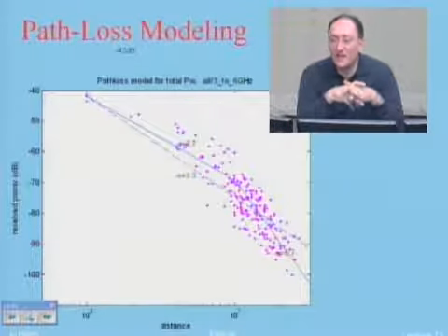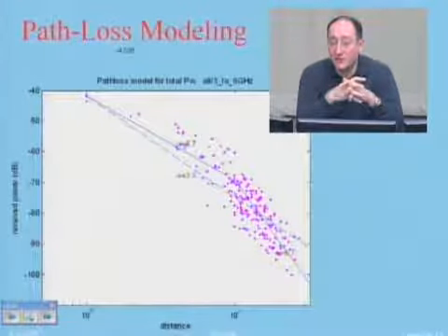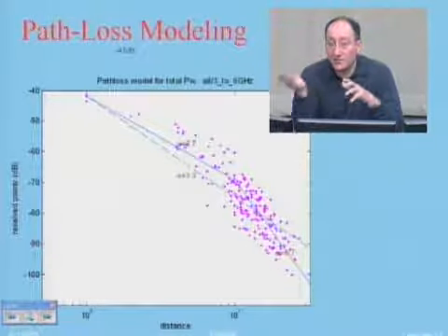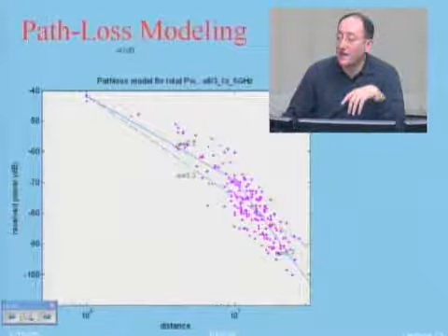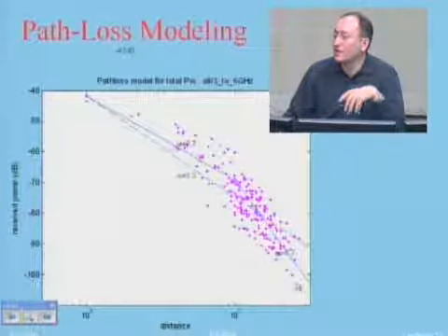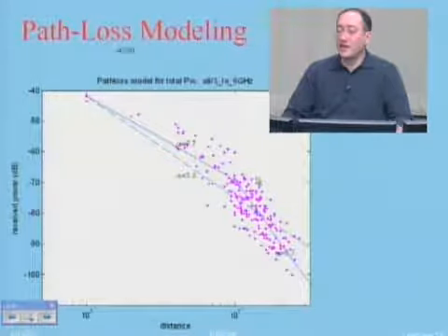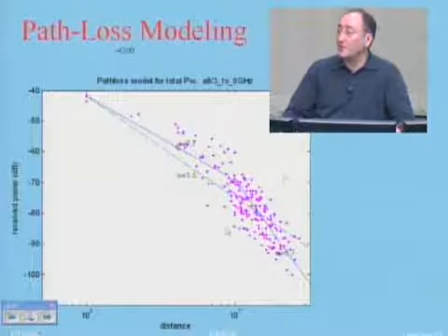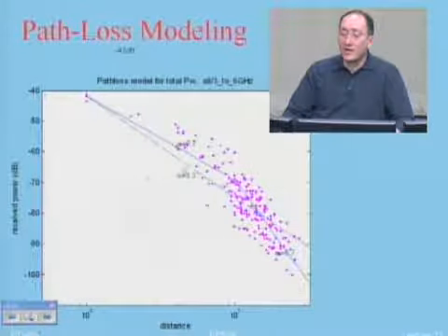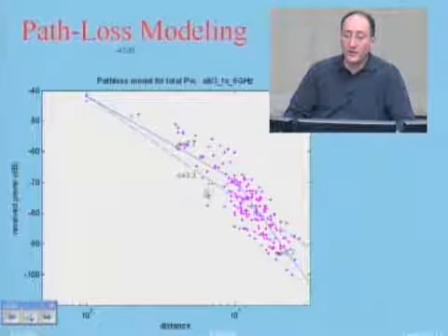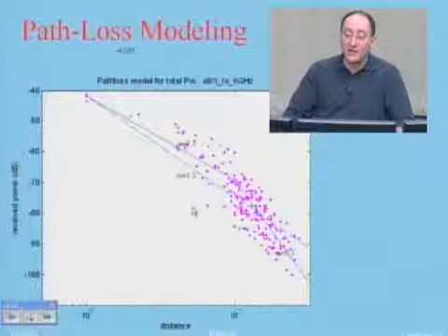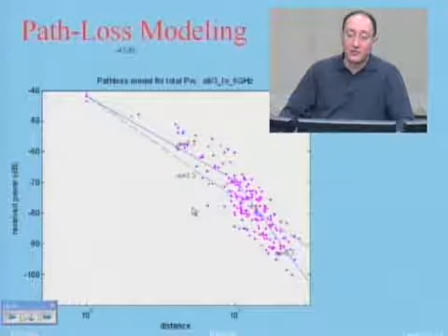Because up to the place where I hit the walls, I'm like free space, and my distance power gradient is around 2. After that, it starts to decay rapidly. So this is what I have in here. And 802.11, ultra-wideband, and 802.15, all of them do the same thing. For ultra-wideband, the first person who did this type of measurement and modeling was the group of Professor Schultz, and in particular, Moe Win, who is now a professor at MIT.